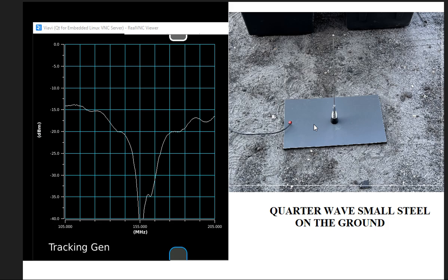After I researched it, I found that when antennas are close to the ground like this, and your ground plane essentially binds itself to the earth itself, that it essentially acts like a giant sponge. So a lot of this radiation, instead of going out and radiating everywhere, a lot of it will be absorbed in the ground and nowhere near as much coming out as you would think. So be careful about anytime you're doing antenna measurements that you got them elevated far off the ground, because you will get this bogus effect on your return loss.